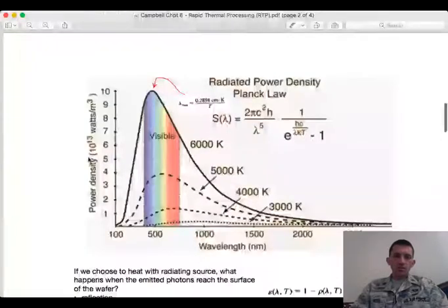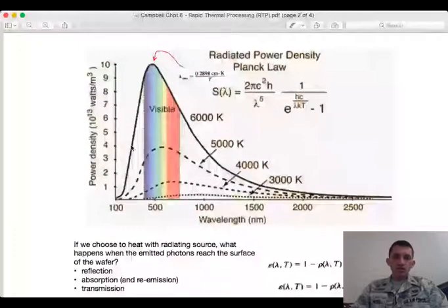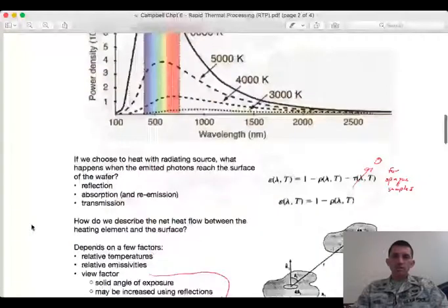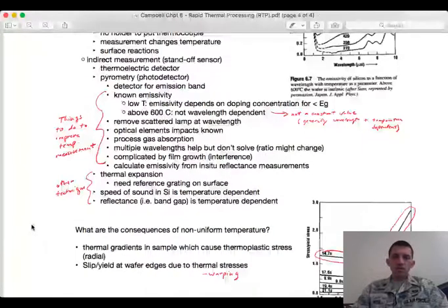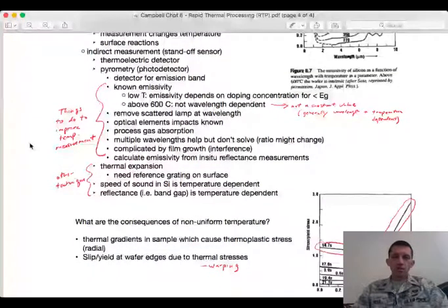On the basis that you have a black body, if I measure it at this wavelength and at this wavelength, then I can fit a black body to those multiple points and extract the emissivity from the measurements themselves and not have to know much about the material otherwise. But that's not as helpful as you might hope, because that assumes that you have a constant ratio between those multiple wavelengths, which might not be true either.